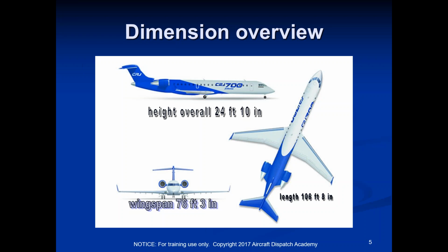As you're flying through the air, if you add rudder, it will help you adjust for the wind. If the wind is blowing you this way, but you still want to maintain this heading, then you have to put in a little bit of rudder to fly this direction. How many of you watched that crosswind landing video? You notice all the planes come in with the nose pointed straight this way, and they're flying like this. That's the rudder that does that. You have so much wind pushing the nose of the plane over, and you're still trying to maintain going straight, but what they do is leave the rudder out there like that.